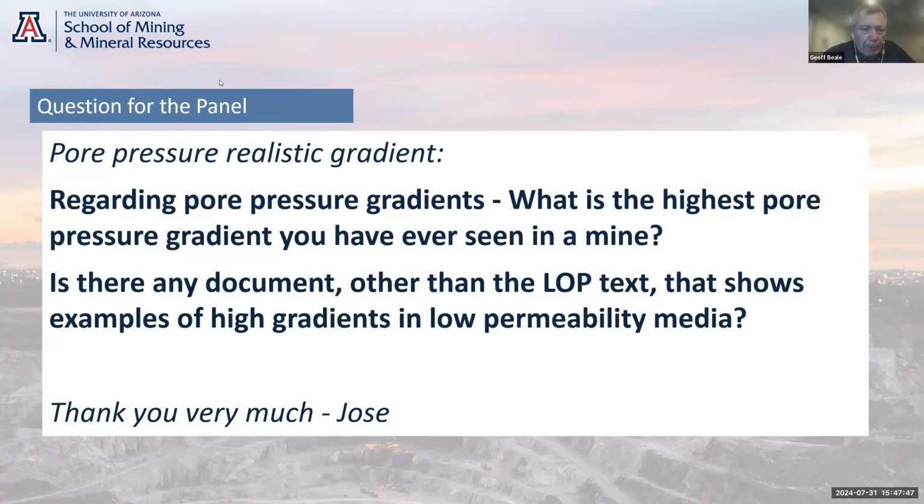The piezometer in the sand didn't change because when the load compressed the clay, the sand was permeable enough that the water flowed away. So we had two piezometer sensors separated by 2.5 meters with 65 meters of vertical head difference between them. That's probably the biggest situation I've ever seen.